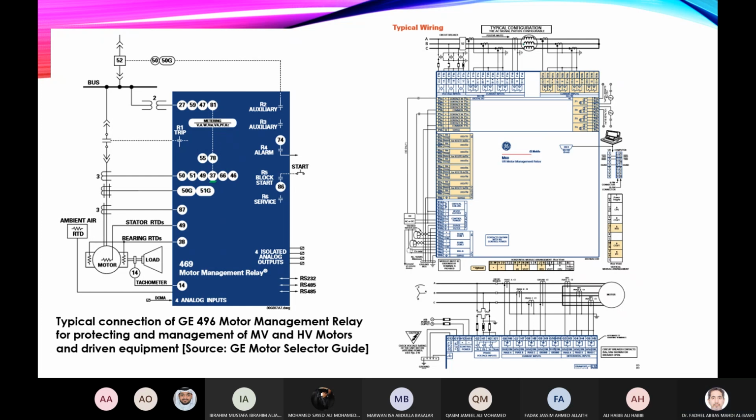Now we have, this is the motor connected as a star. We have CTs before the star point and CTs at the beginning of the terminals. This is because I need to implement a differential protection. In addition, I can have an overcurrent protection through these CTs, and this is the core balance CT, which is dedicated for ground fault protection. And this is the circuit breaker now, okay?